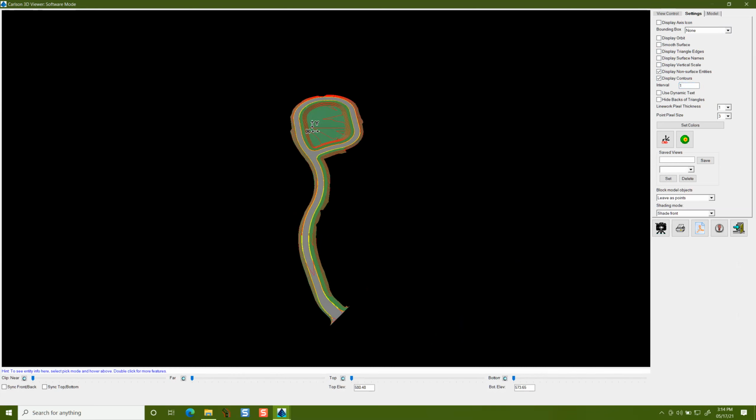Well, that's another possible point. I don't know if it's following the profile. Oh, it's not following the profile. Somehow we lost a profile. No, that's the profile. There's that 100 foot vertical curve. There's a 2% up, a 0.5% out, and then a nearly dead flat, but a little bit.